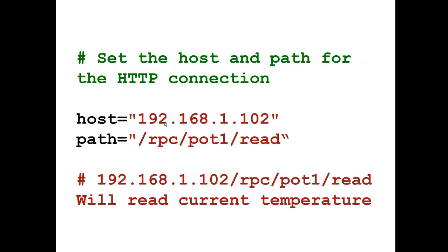Like for example, if I say 192.168.1.102/RPC/port1/read, this is one single command together. When we give this GET command to the microprocessor, it will simply read the temperature value in numbers.